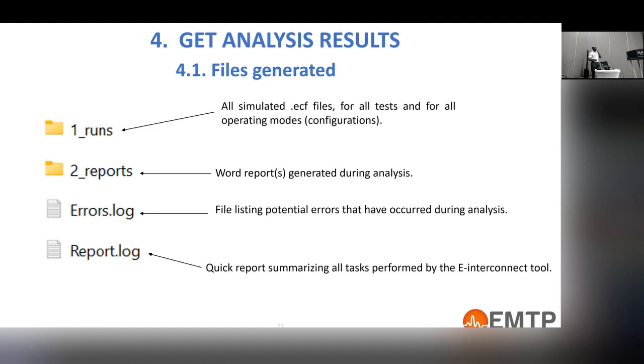In terms of results, actually, we have a folder which is created that will contain all the simulated files. So if your analysis requires maybe 100 simulations, all the simulation files will be generated inside this folder. There is this other folder that contains the report. It's a Word report. If you have one report, you will have only one file here. So this is simply an error file. If any error occurs during your analysis, you will have the description of the error here. And this is also simply a log file. If you want to understand each action that the tool did, they are summarized here inside this report.